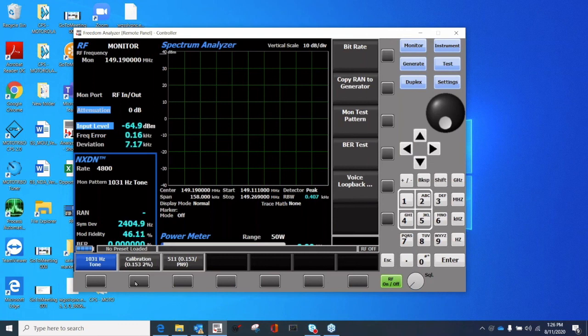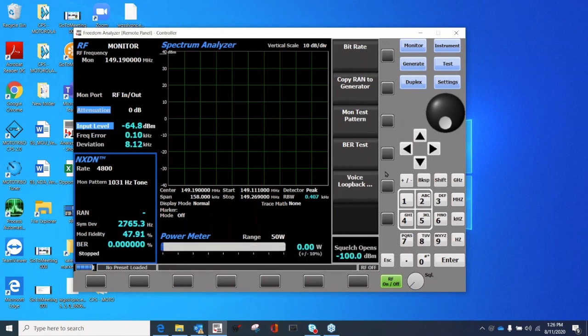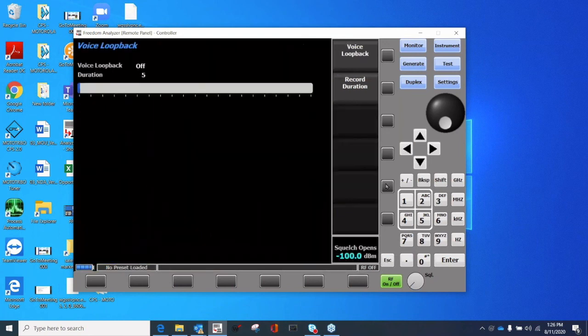You see the icon on the Kenwood manual. You see where I can use those calibration codes. I can generate those codes to do this kind of calibration. Okay, let me escape from this. Actually, I can do a voice loopback. The voice loopback is a good way to test the vocoder.